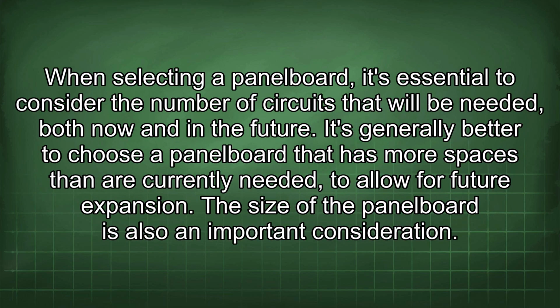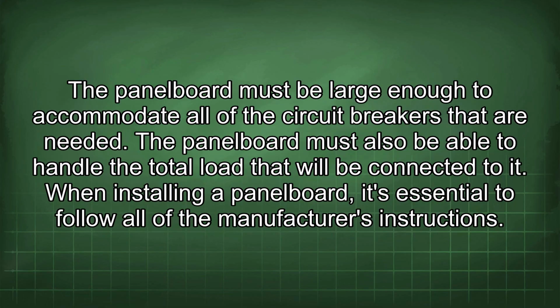When selecting a panel board, it's essential to consider the number of circuits that will be needed both now and in the future. It's generally better to choose a panel board that has more spaces than are currently needed to allow for future expansion. The size of the panel board is also an important consideration. The panel board must be large enough to accommodate all of the circuit breakers that are needed. The panel board must also be able to handle the total load that will be connected to it.